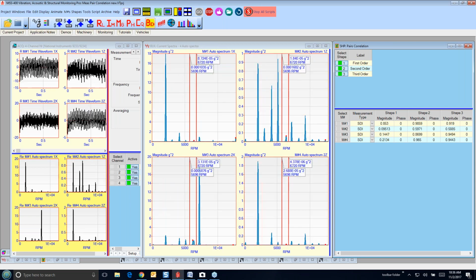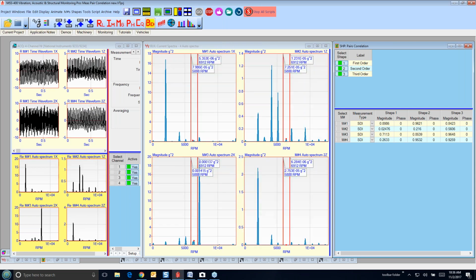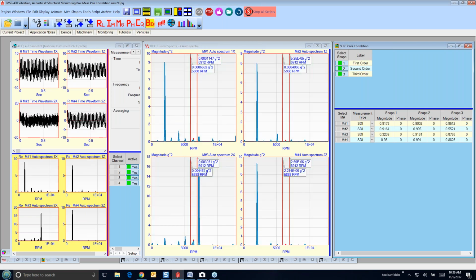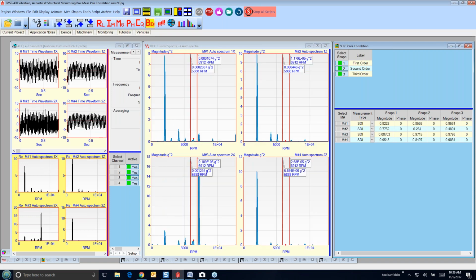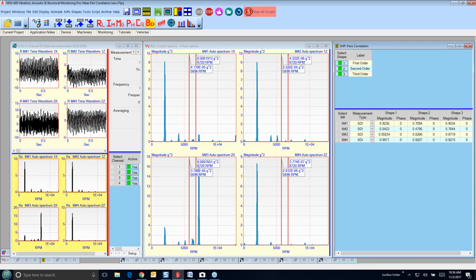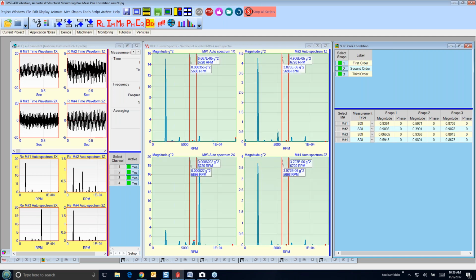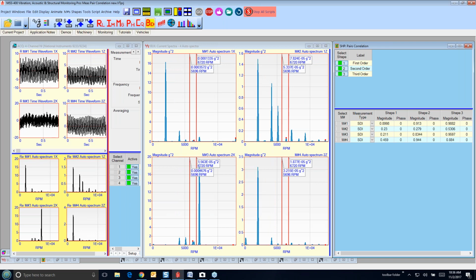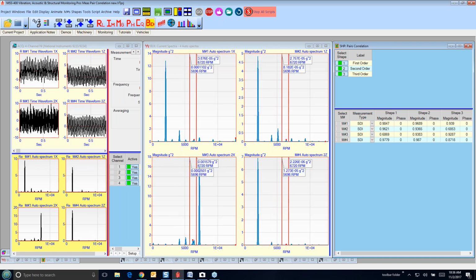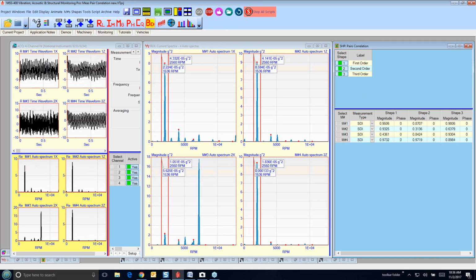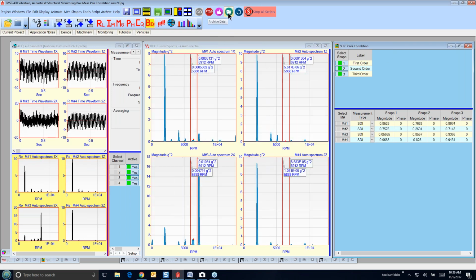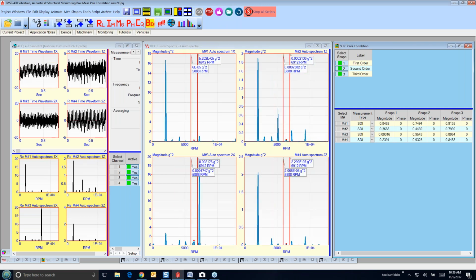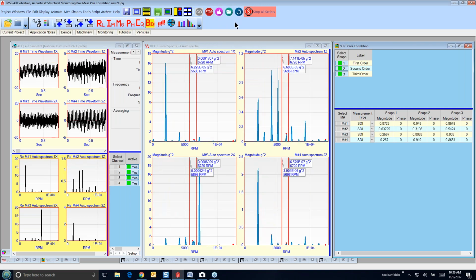The bands are 1,000 RPM wide, so we can have the machine move around a little bit in terms of the speed and the running speed in these orders. And what we're doing is grabbing the peak of the running speed and then multiplying by 2 and by 3 to set up those other 3 bands. Okay, so this is all working. I'm going to push the button here that says archive data. Now it's going to start putting data into our archival database.